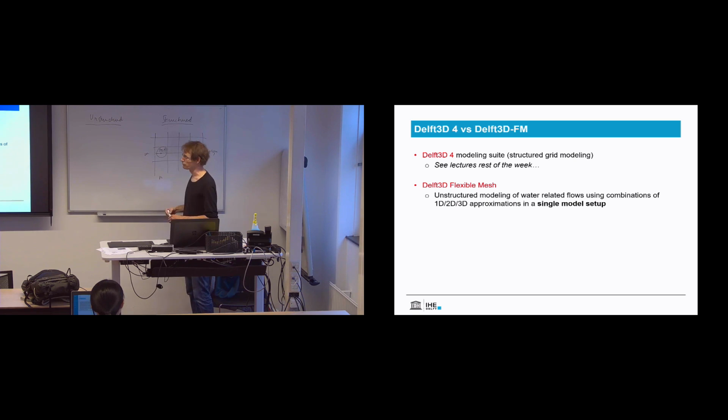That's why if you refine a structured grid, you have to refine it over all the columns. And if you want to refine a column, then you have to refine it over all the rows. You saw that when you made that wave model. You had a little zone of interest where you needed more resolution, but as soon as you refined that, you saw that it spread out over the entire domain. That has to do with this matrix structure.